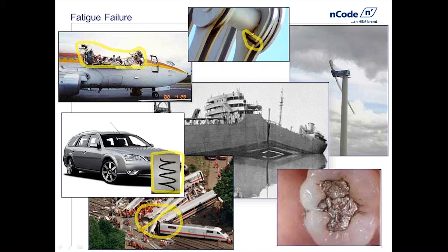load fluctuation, or actually it's very interesting on a bridge. A very common stress cycle on a bridge is due to temperature. Heat up and cool down once per day. Cool at night, and a hot or hotter solar load during the day causes the top of the bridge to expand relative to the bottom and can cause huge stresses. We'll talk a lot about stress cycles and what causes them and the impact of them as we look to the rest of the day today.